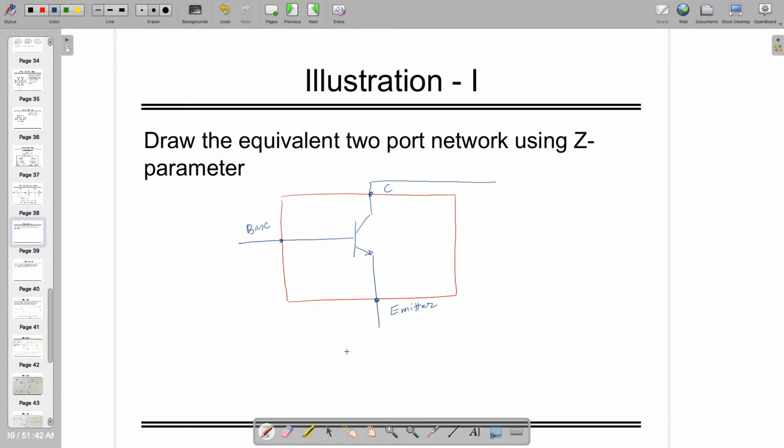This is a current controlled device. You are giving current at the input, IB. On this side, IC. Generally, this one is, let's say, ground. I know the following equations. IC is equal to beta IB. IB is equal to I0 exponential VBE by VT, minus 1.